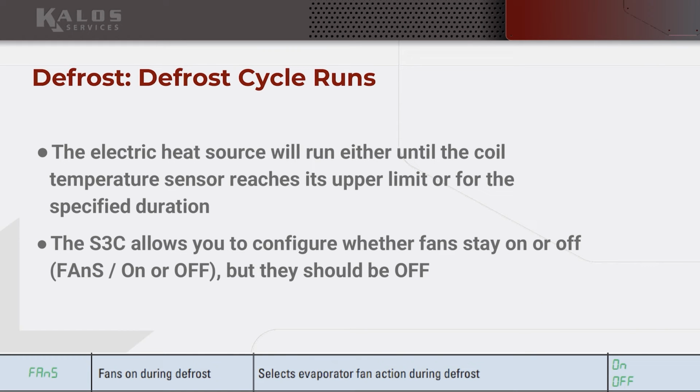Okay, so in the S3C controller, that early termination sensor is provided by a resistor style input, right? We talked about that last week, where we read the changing resistance as temperature changes, and the solid state controller understands that to mean that heat or cooling is either increasing or decreasing, and then we'll kill defrost based on that.